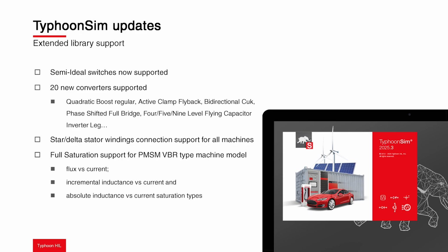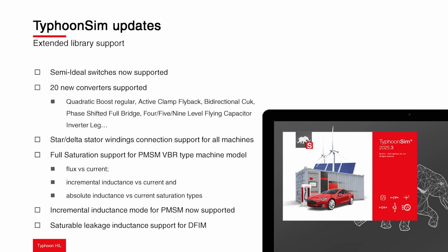Beyond this, in TyphoonSim, full saturation support for PMSM VBR type machine model is available, as well as incremental inductance mode for PMSM and saturable leakage inductance support for DFIM.